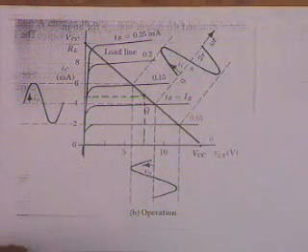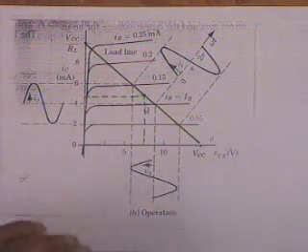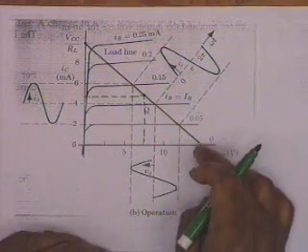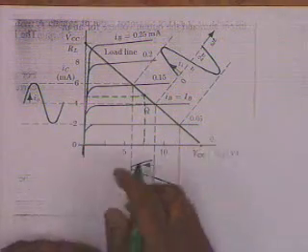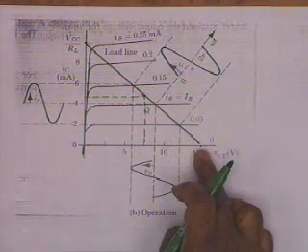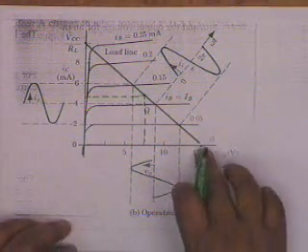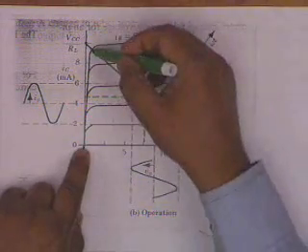What is the corresponding collector voltage variation, collector swing? It's slightly asymmetric. We can go right up to, you see, the zero base current is here. Zero base current is here. That means ICBO is approximately 0. So we can go right up to 15 here. But can we go right up to 0 here? No. Because the current is here.